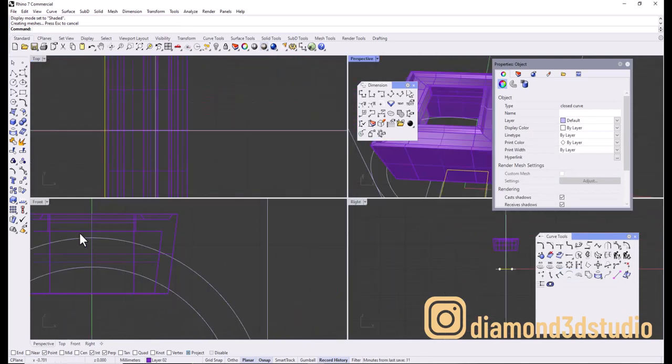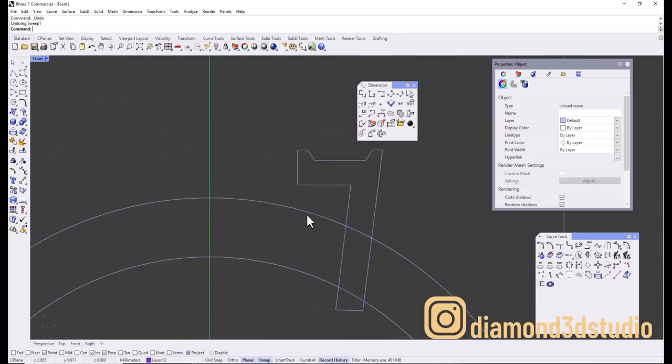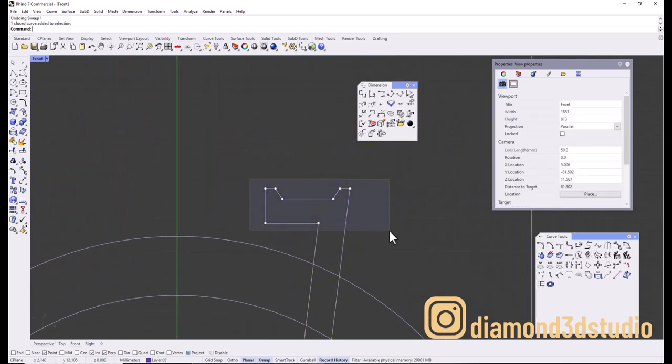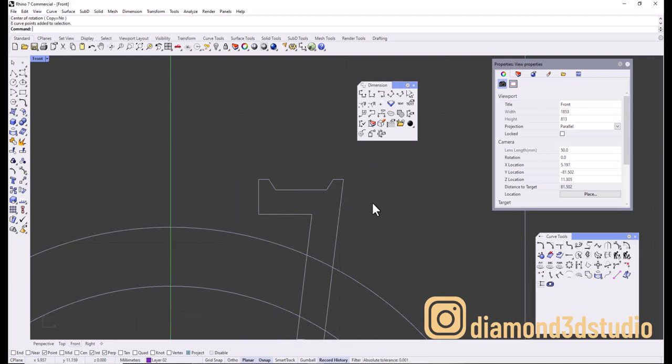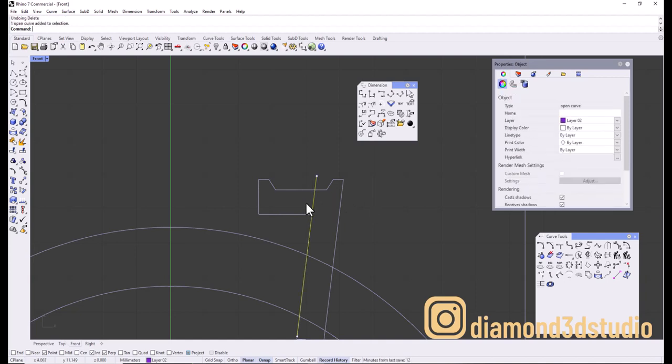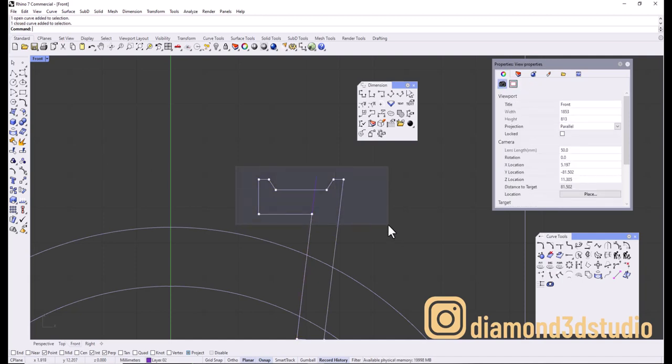All right, now something I want to add here is, in case you need this profile to be a bit slanted. Let me go one more step back, because we might need again to fix the thickness. Once you have this profile, select all the points together and just rotate this around, let's say 5 degrees, something between 5 to 10.